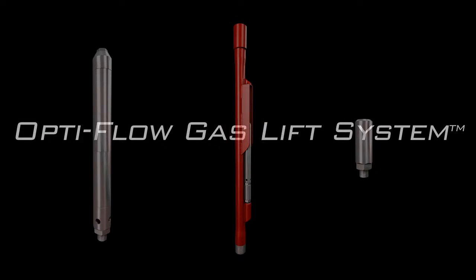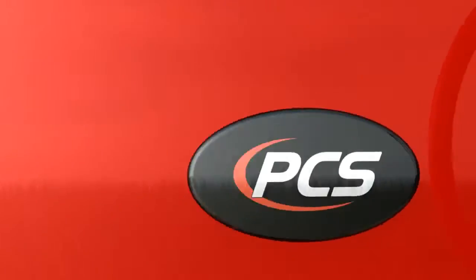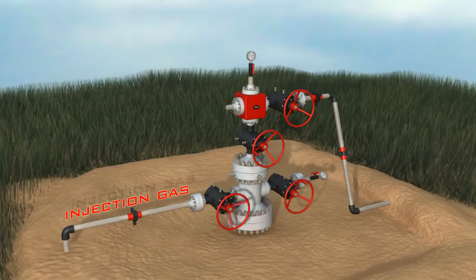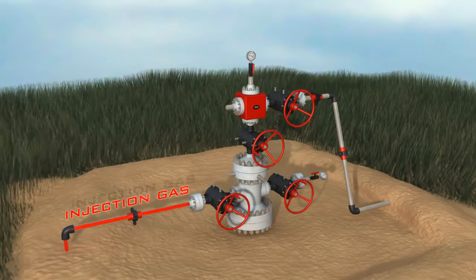The OptiFlow gas lift system by PCS uses a high-pressure source at the surface to inject gas down the annulus into the tubing. The compressed gas is injected into the production stream through gas lift valves fitted in integral mandrels. The mandrels are installed as part of the tubing string and are positioned at prescribed depths.